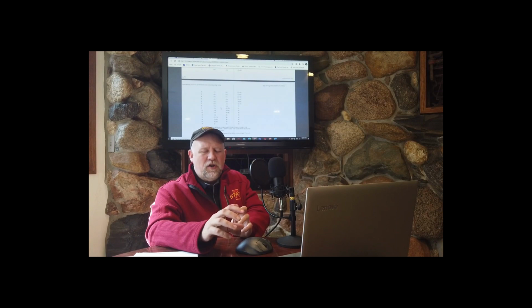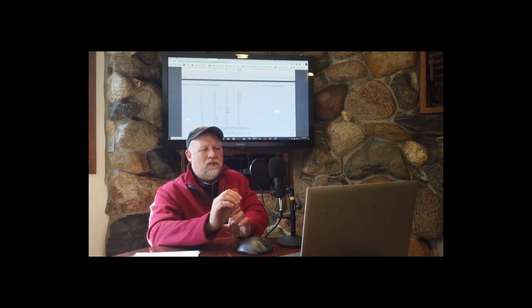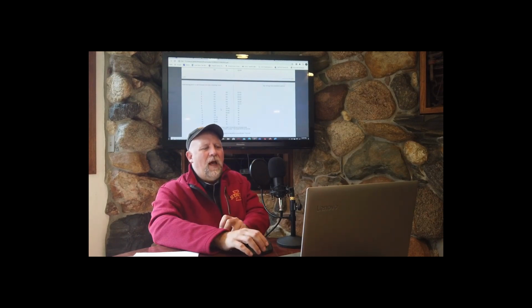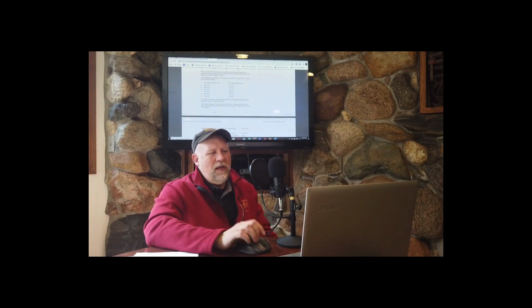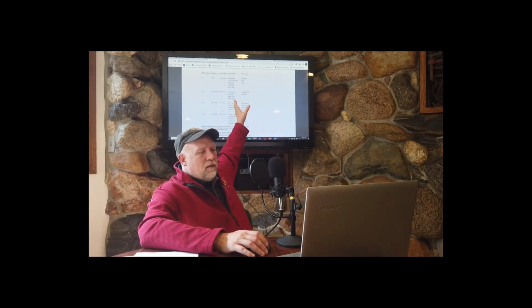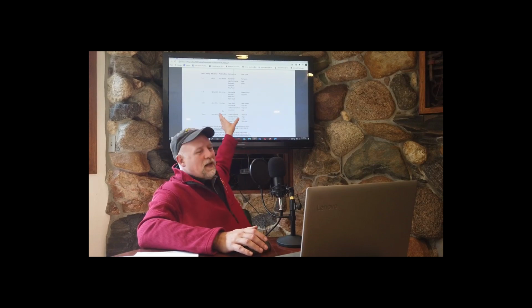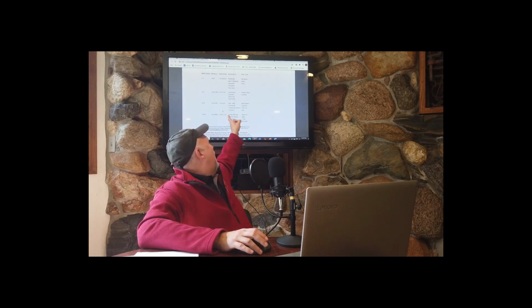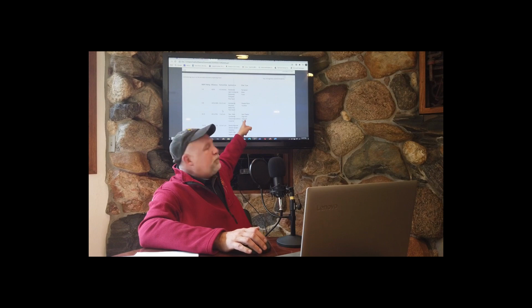And when you go to purchase a new filter, we're going to purchase them based on their MERV rating. I don't need you to know all these numbers and microns and sizes and groups of particles. What I do need you to know is this next page, where it has MERV rating. Kind of ignore efficiency. If you found an old filter, that's kind of what that would be compared to. And then what I really want you to know is the purpose and type over here.